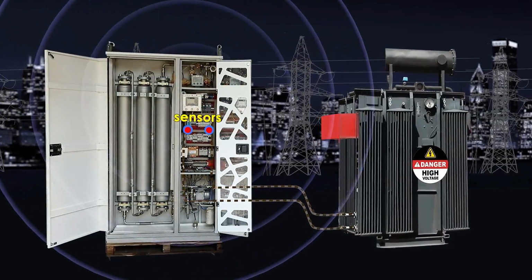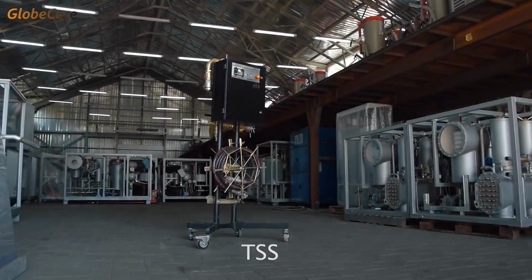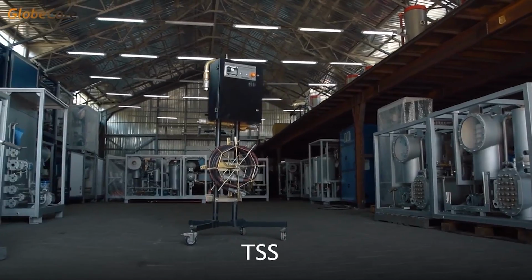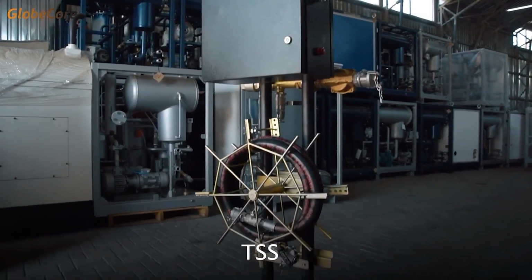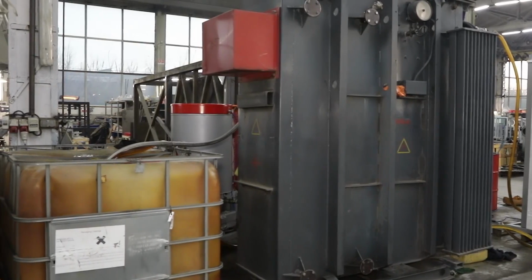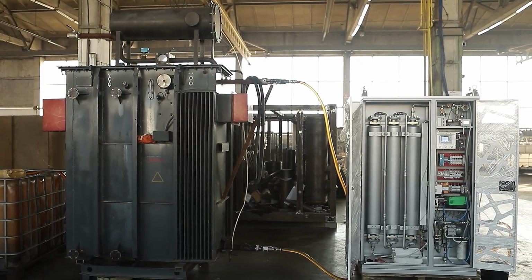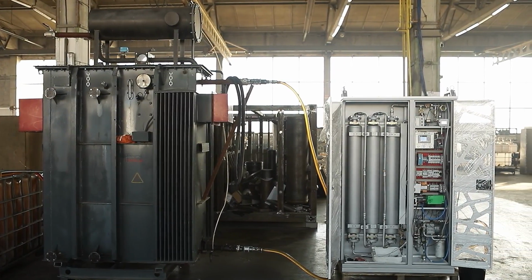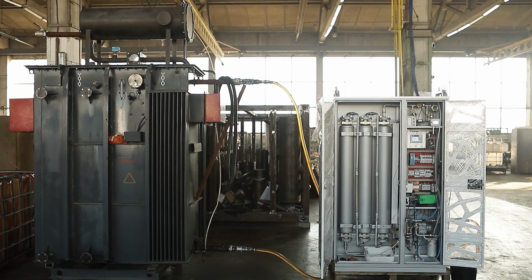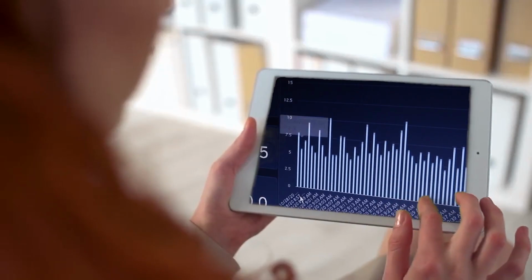The TOR system is additionally equipped with a TSS module. The TSS system allows you to connect powerful degassing and regeneration machines to the transformer in a matter of minutes, after which the TSS monitors the oil level in the transformer. This allows degassing operations without shutting down the transformer. As an option, oil purification can be engaged or disengaged by the operator on a running transformer. This is done remotely using a computer, a tablet, or even a phone.